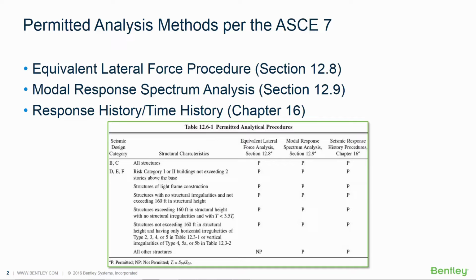Before beginning, you should review Table 12.6-1 in the ASCE 7 to determine which analytical procedure is appropriate for your particular structure. Now for our training today, we are going to assume that the equivalent lateral force procedure is not permitted, so we'll be using a modal response spectrum analysis.